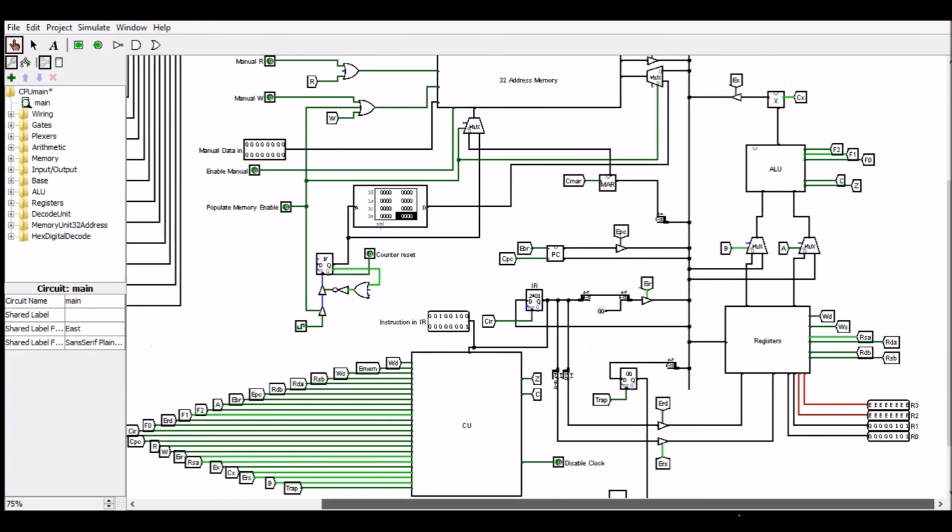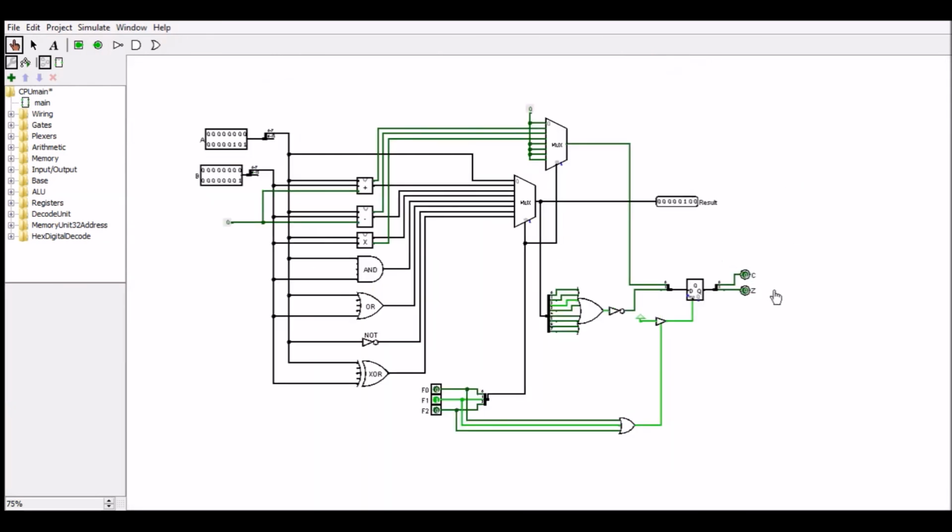So we're reading the source to A, and that's in the 0 input to the multiplexer, so A is not enabled, and that will flow into the ALU. And the literal 1 from the instruction register should be on the bus, yes, and it's flowing into 1 here in the multiplexer, so B needs to be enabled. These are all set by the control unit here, and we should be able to see that the subtraction has taken place. So we've got 5 here, we're subtracting 1 from it, and the result is 4. Because of the opcode, the subtraction operation is chosen.